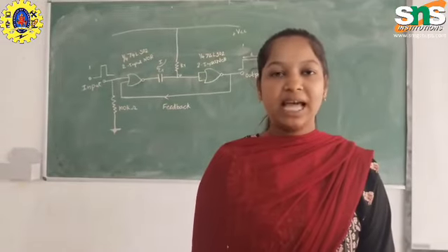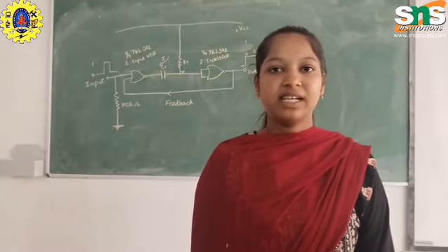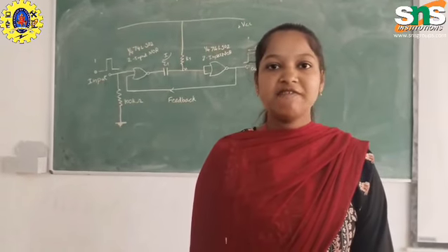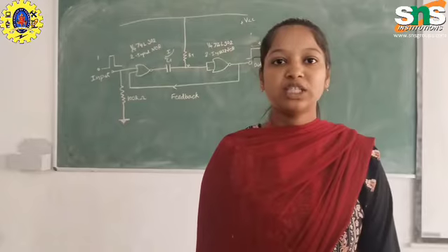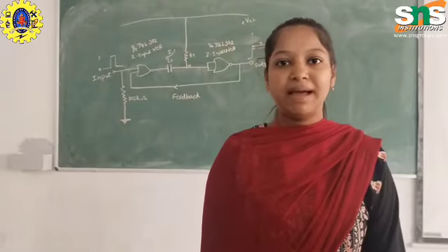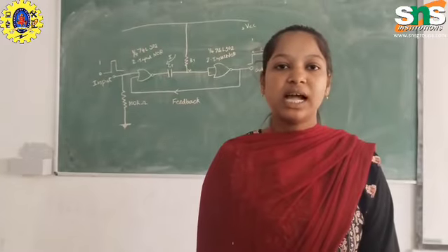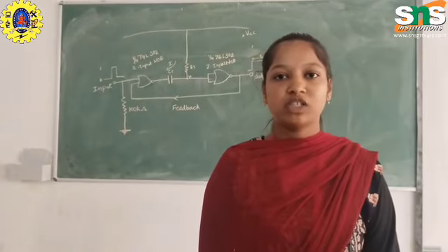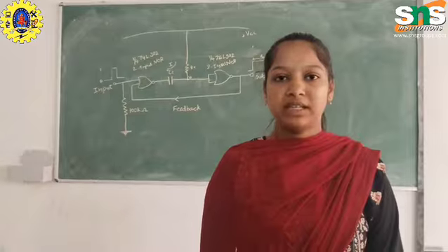Monostable multivibrators have only one stable state, hence the name mono, and produce a single output pulse when triggered externally. Monostable multivibrators only return back to their first original and stable state after a period of time determined by the time constant of the RC coupled circuit.